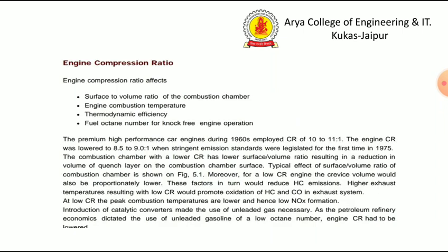Engine compression ratio. The engine compression ratio affects the surface to volume ratio of the combustion chamber, engine combustion temperature, thermodynamic efficiency, and fuel octane number for knock-free engine operation. The combustion chamber with a lower compression ratio has lower surface to volume ratio, resulting in reduction in volume of quench layer on the combustion chamber surface.